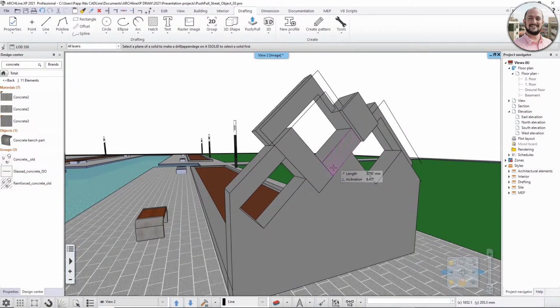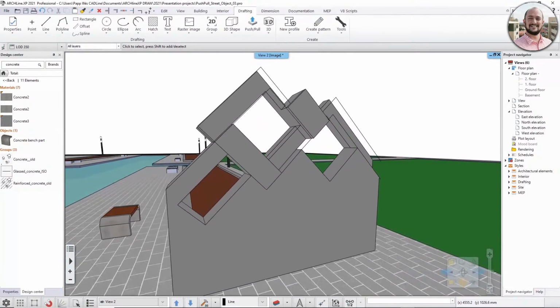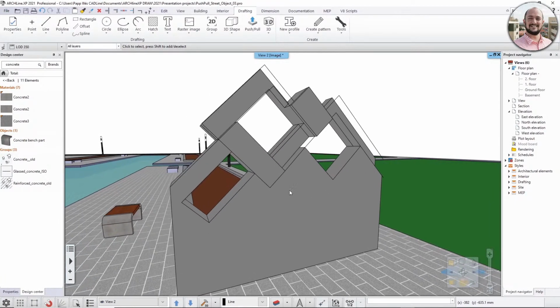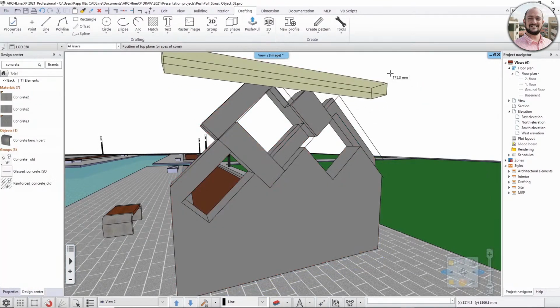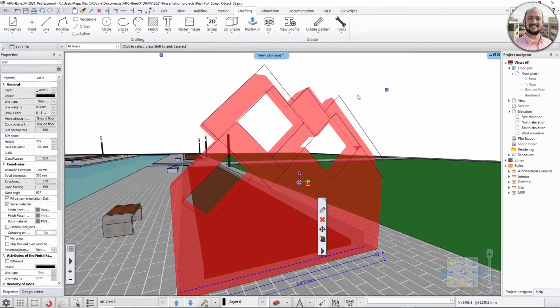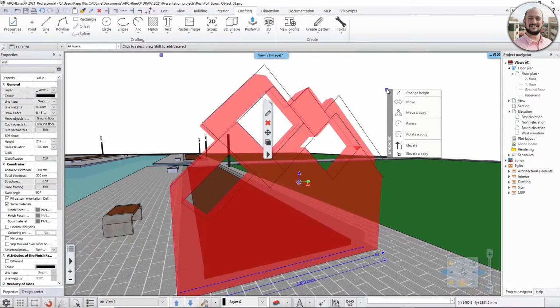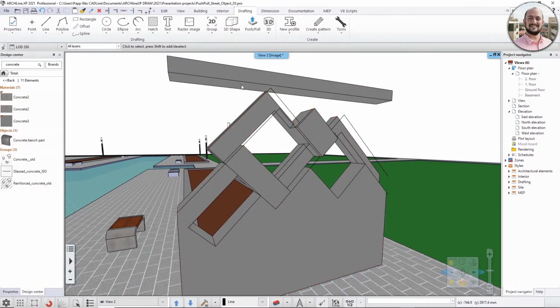The very good thing with this is that once you have something like this, it is part of the wall. So what I have now is kind of a parametric extension of this wall. Whenever I change, for example, the height of this wall, because I would like to make it a little bit smaller or higher, see, the complete thing was kept, only the top was chopped off because I made the wall smaller than the original was. But if I make it a little bit higher, then because I modeled this part to be chopped off, the rest will be created again because it is above the contour that I have defined.